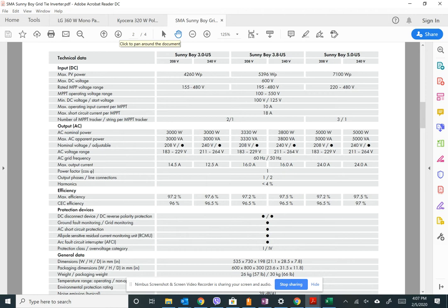Now, what we have here is 5,230 watts output, and we can see that the PV max power, which is right here, is what we calculated is too large for that model. Okay, so then we go up to the next one, which is right there. Okay, cool.